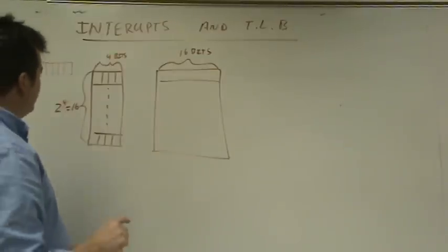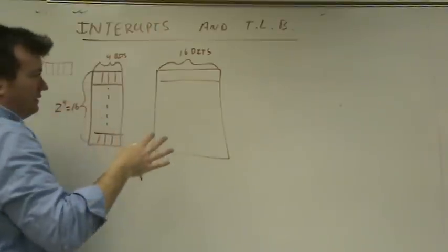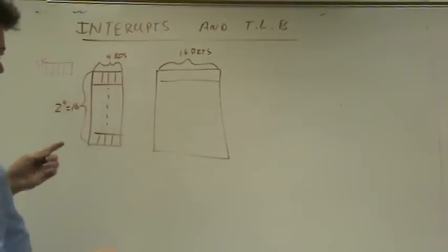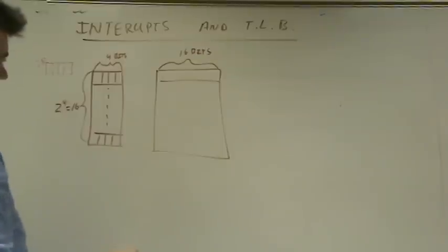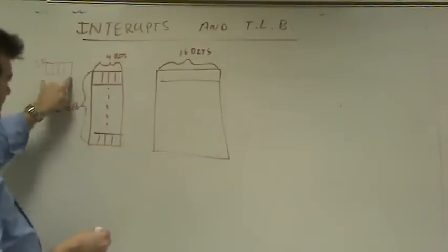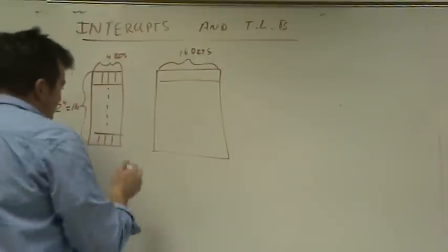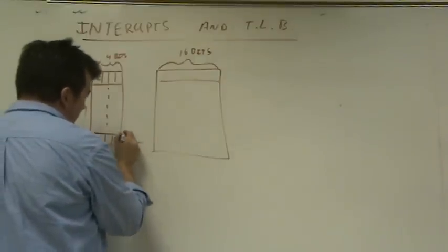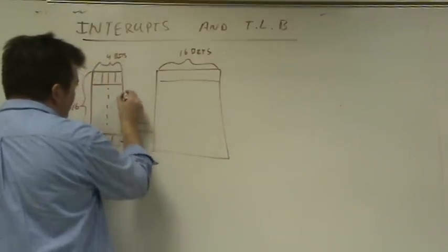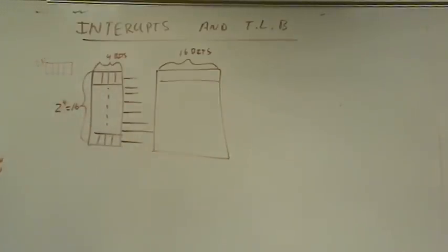So what we'd like to do is say if somebody puts a number in the instruction register that's other than 0, a power line will turn on, which will then cause us to kick off that piece of hardware we drew before that says, do these 4 bits match any of these 4 bits exactly? If so, remember these each had a power line coming out of them. Last time we had 2, but now we have 16 power lines coming out.